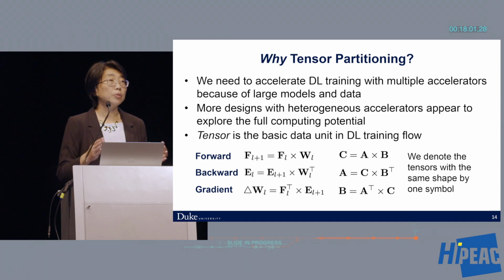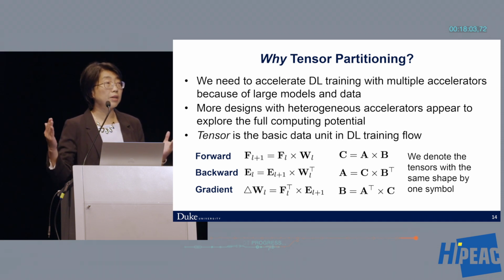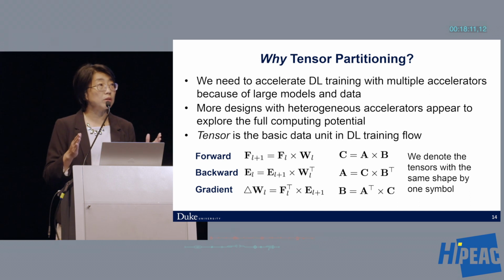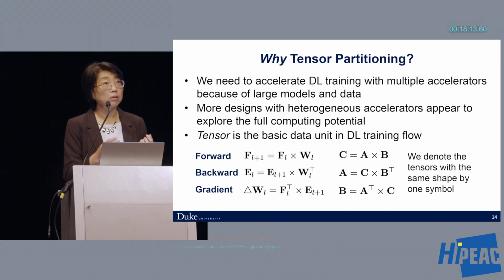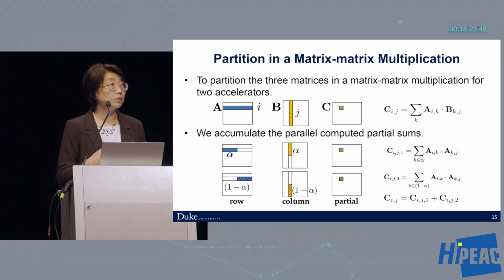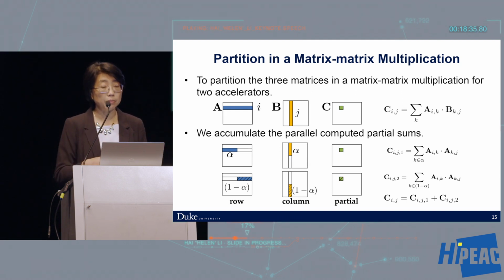Particularly here, we ignore the activations and normalizations because, based on hardware tests, matrix operations consume the most power. And we are talking about accelerator designs, which also primarily target the layers. So when we talk about large DNN execution, we are essentially talking about how to partition the matrices across different accelerators to achieve parallel computation.